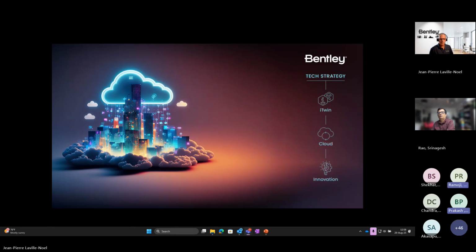See, in ORD 2024, there is an option of nudge. If you use that nudge and the result is not satisfactory, do we have a choice to go back or undo it? Or else normal Control Z will work for that. I think the normal undo will work. I didn't check this, but yes, once you exit the nudge tool, if you undo, it should come back to the previous geometry. I must check.